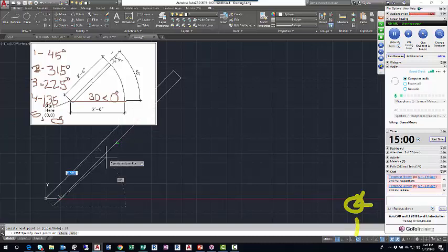And then finally, I could close this, but I want to do 2 more lines, not 1 more line. So I'm going to point at my UCS icon with my crosshairs, and when I see my tracking vector, again I'm going to check my polar tracking tooltip. I want a 135-degree angle. When I see that, I'll type in 1.75 and press enter. Now the extra line I'm adding is at a 0-degree angle, and it's going to help me place the arc that will indicate the door swing. So I'm putting my crosshairs right on the red horizontal grid line. That's the 0x or 0y, whichever one you want to call it.